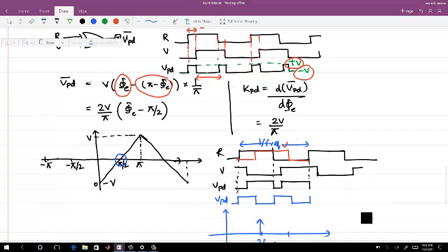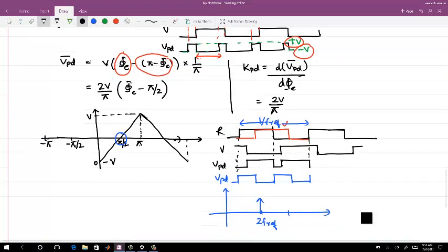This is also used at different places. But again, all these phase error detectors cannot correct for a frequency beyond a certain range, so one has to look for that. To summarize this part, the range is minus pi by 2 to pi by 2, I'm writing it after the shift, and it has a linear gain. This is the particular PD.